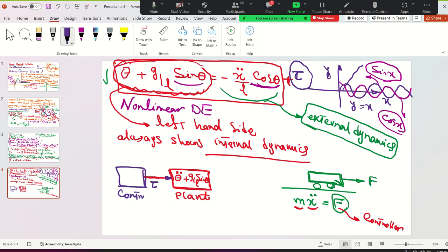Controller. We show it with C. And the plant we're going to show with G, capital G. This is convention. I'm applying a torque from the controller, it goes inside the internal dynamics of the plant. When it does, you're going to see the effect of that as a real output, theta real. This R is real, the real angle of your Lego robot.